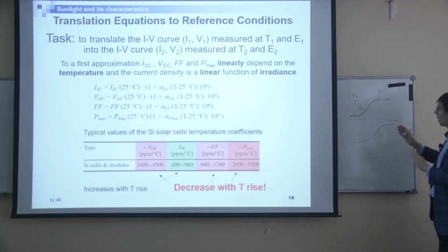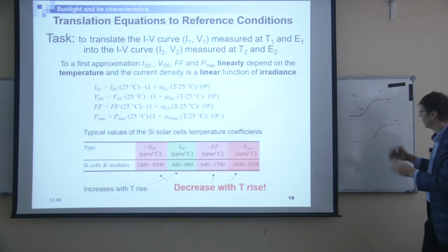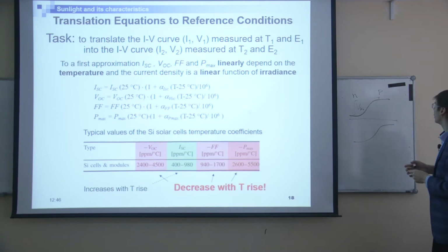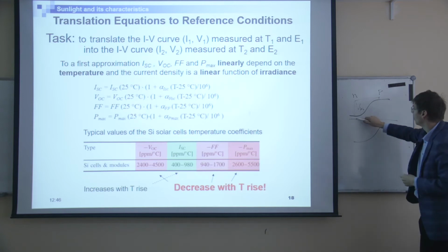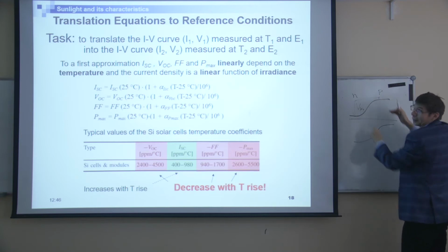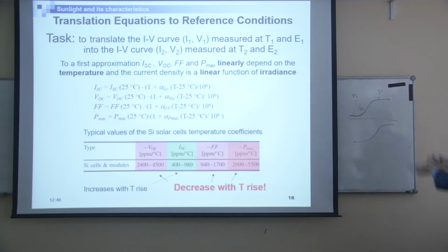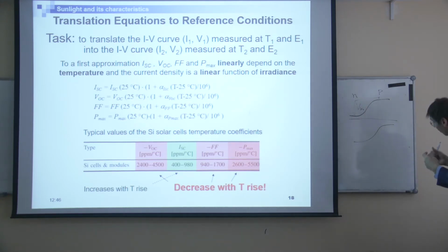Actually, it's not always the same, but the higher you have this bending, normally the higher you have a VOC. So you can increase the doping of each layer. If you increase the doping, the Fermi level goes nearer to the nearest band, so you have an increase of this band bending. But with the temperature, the concentration of the electrons and holes in equilibrium is the same.